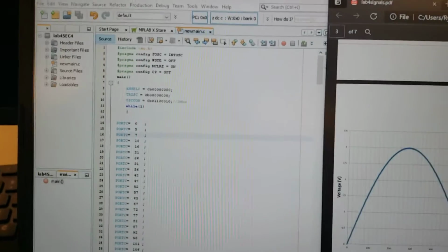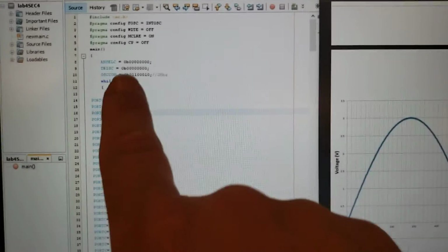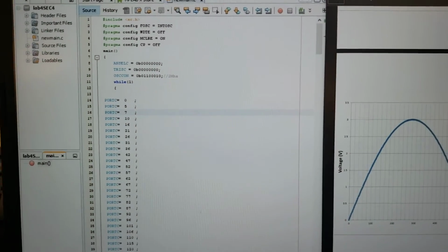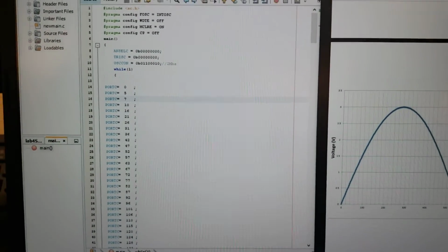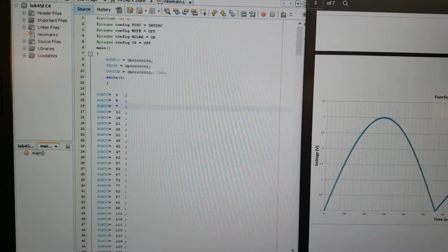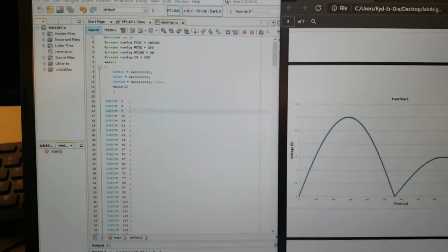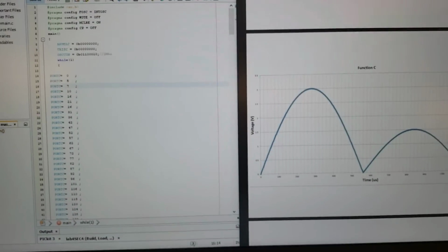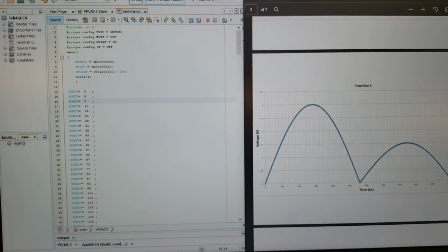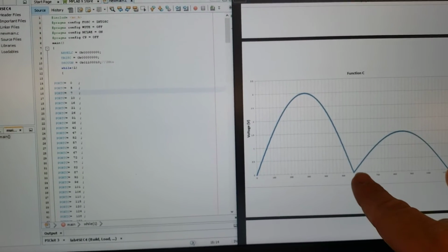To achieve this, we use the knowledge we gained from previous lab that at a 2 megahertz clock cycle shown here, the port function takes approximately 3.94 or 4 microseconds to perform its task. We took the 560 microsecond duration of each of the sections of our synthesized sine wave.